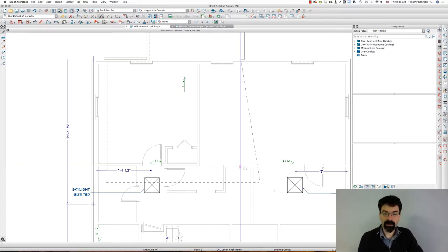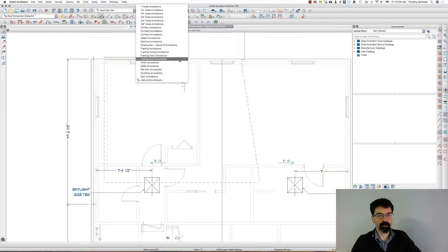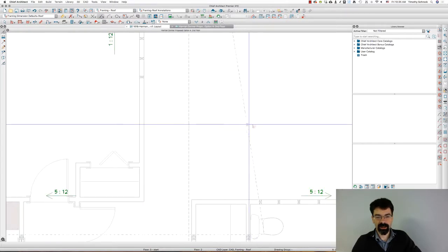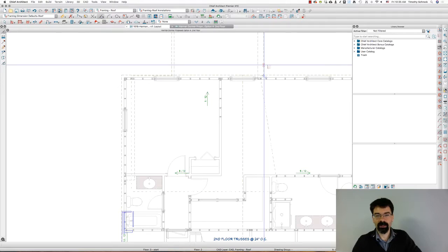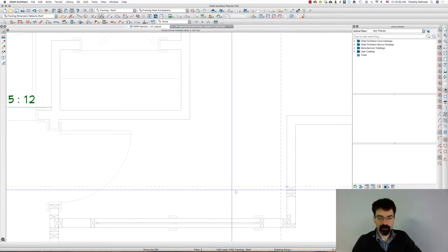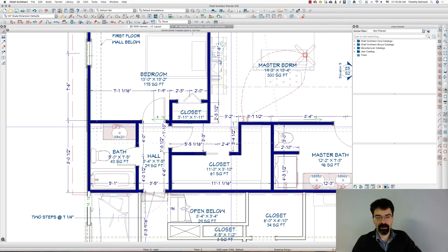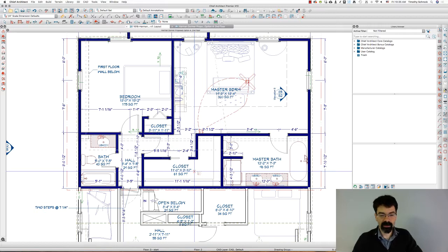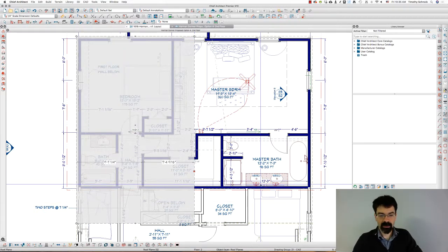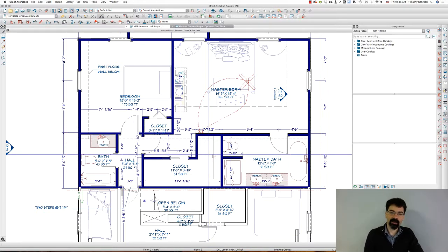Now that line, that polyline, it's just a CAD line. It's going to appear properly in all of my layer sets, because let's go to framing roof here. You can still see that dashed under there. Now in the framing roof layer set, roof planes are dashed already, so it's a little bit different. I could go to default set, and roof planes are on there. And the great thing is, in my default set, let's say I don't want to see roof planes here. So I'm going to turn off roof planes. And now that line is gone as well. So I've got control of that line.